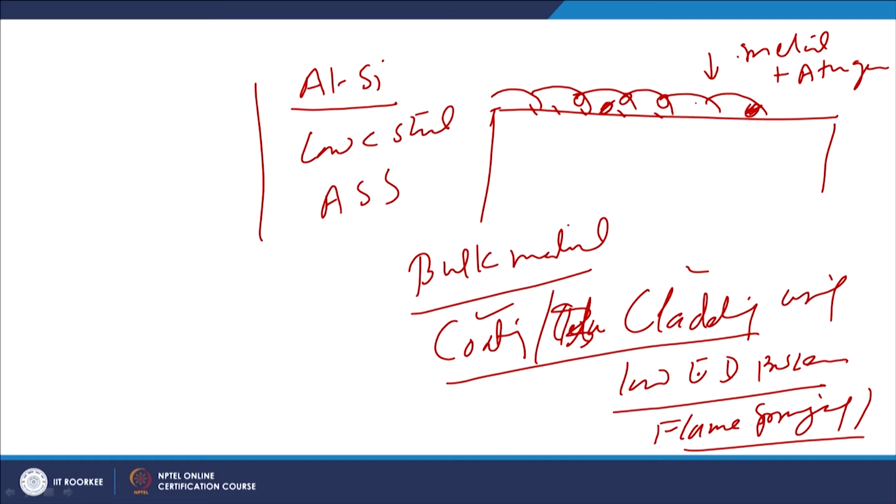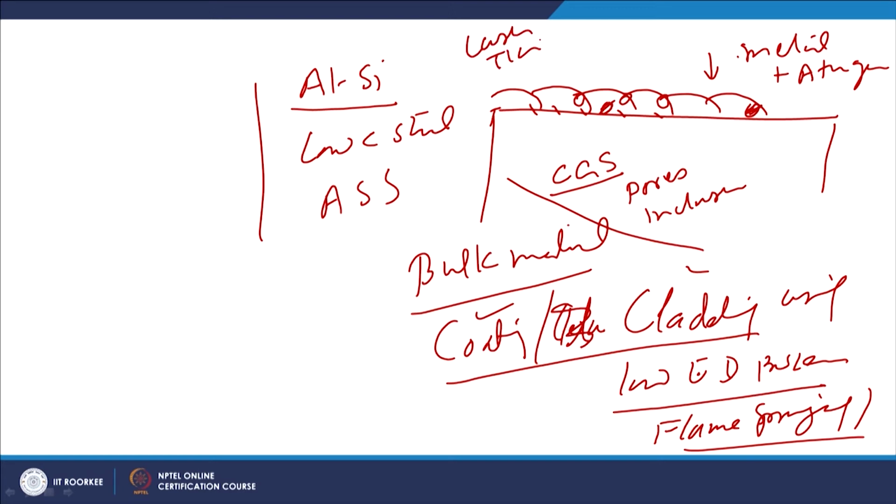So, because of these issues like coarse grain structure, pores, and presence of inclusions in flame sprayed coatings, when they are subjected to remelting by laser, by TIG arc, all these inclusions will start floating over the surface. Porosity will be eliminated because of the remelting of the metal.